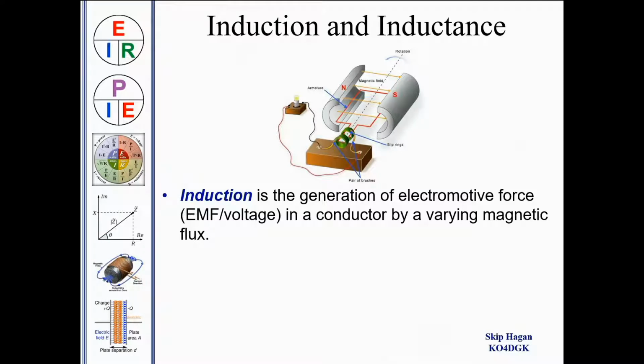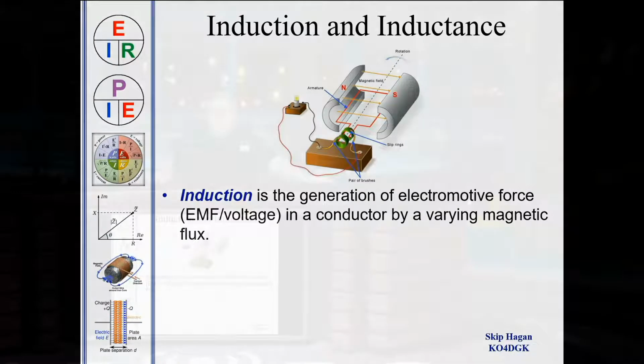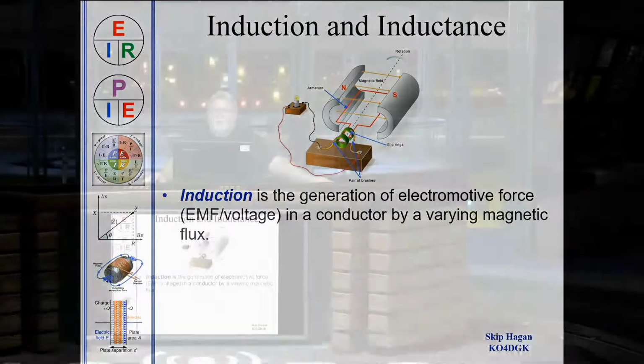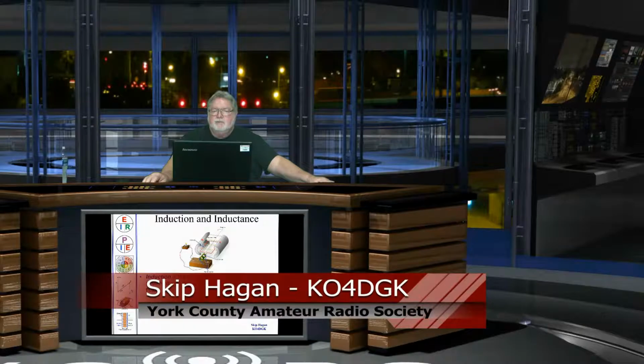But as we continue to rotate, that coil of wire will start to enter a higher flux region, and we'll induce a current flow in that loop of wire. So that's how a generator works. We're rotating a loop of wire inside a magnetic field, and that changing magnetic field induces a voltage and current flow in the wire, through the load, and back to the wire.